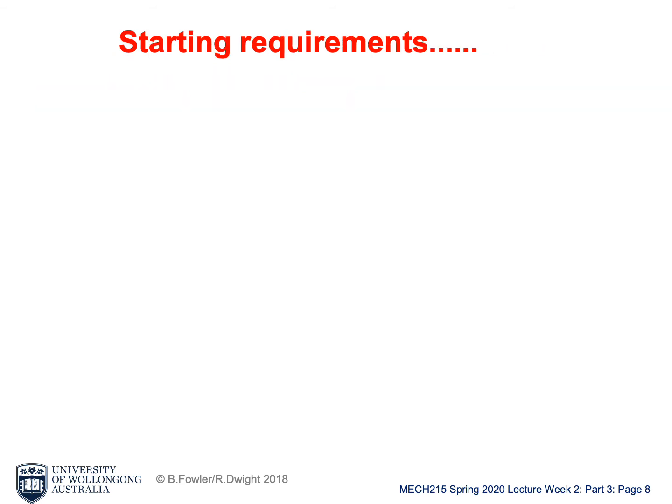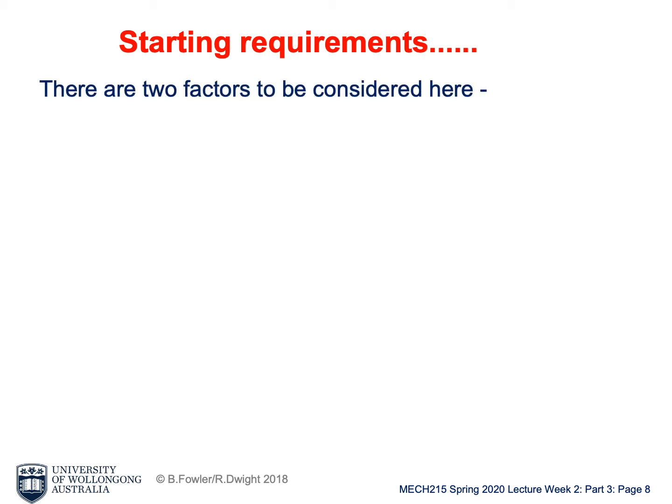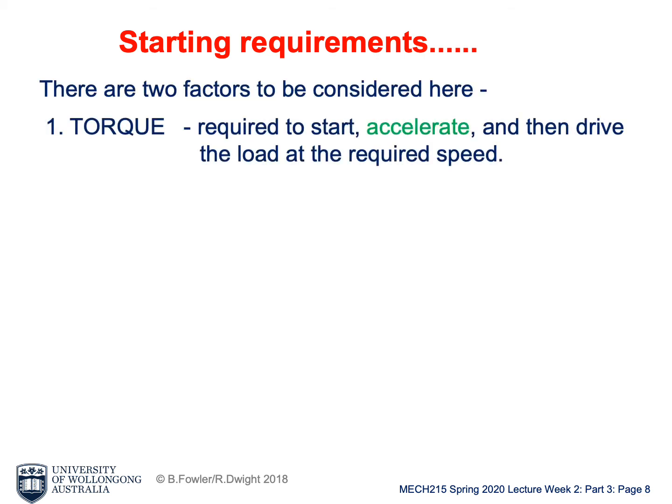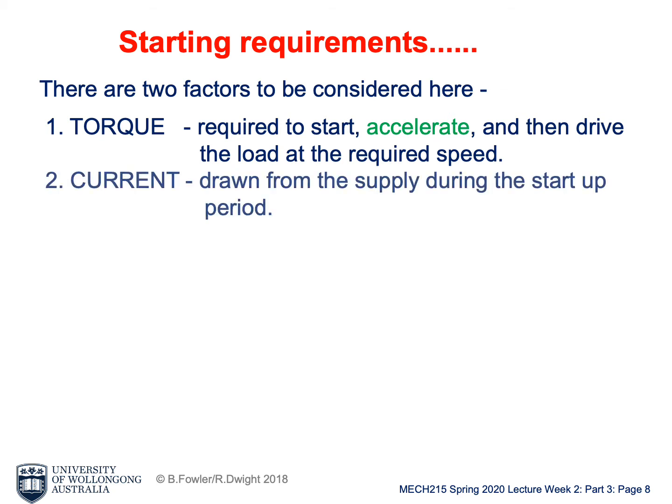After we select a motor for our design requirement with certain RPM and power, we have to consider the starting requirement. Here are two factors to be considered. First, the torque throughout the startup process needs to be always larger than the load torque. Otherwise, the machine will not be accelerating. You will not get to the nominal speed.